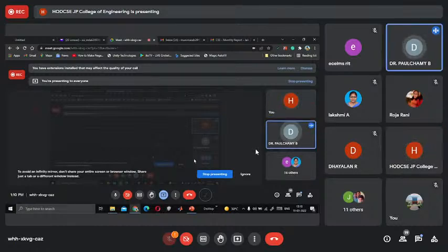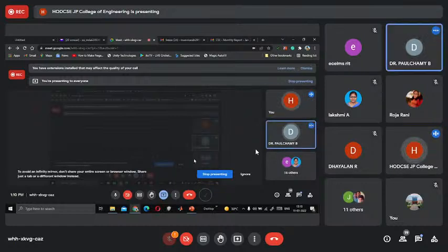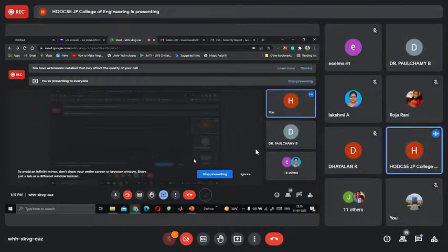During the design of the wearable circular antenna, the return loss is a very important task. Any difficulties to calculate the return loss for various frequencies? No, sir, no difficulties. Here we are using HFSS simulation software. We have also achieved the fabrication level, but I didn't present the fabrication of the antenna here. We have done the fabrication and tested it practically. Both fabricated and simulated results are very good, almost equal.